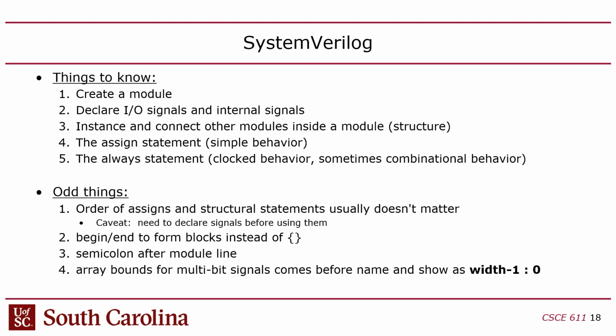So you guys comfortable with that idea? The I/O signals are the signals that come in and go out of the module, whereas the internal ones are just inside, interior signals. And by the way, local signals inside a module are generally used to connect other modules together that you instance inside of there. They kind of act as glue, right?